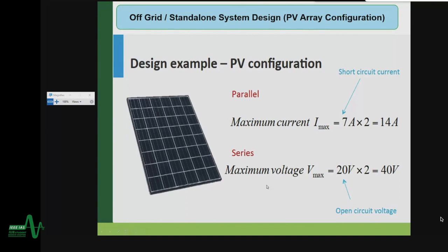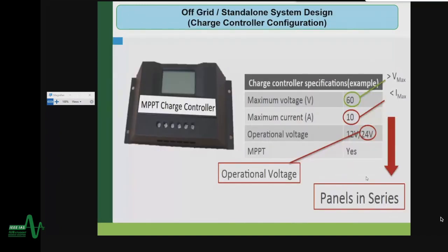And whenever you want to connect all of the solar panels in series connection, so that time choose the voltage. It is 20 volt multiplied with 2, it will be 40. So now comes the charge controller configuration.